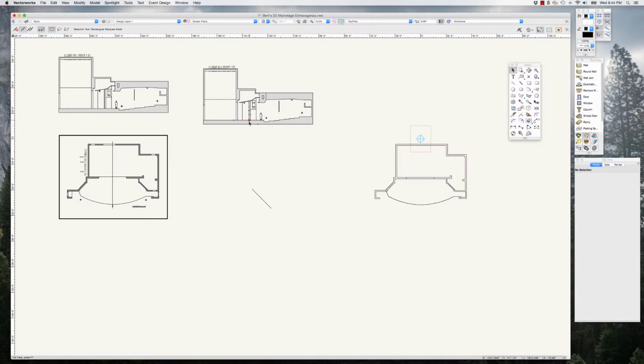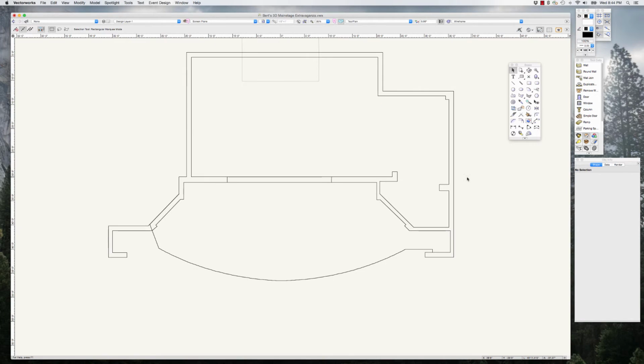The answer is we have to look back at the ground plan, and I need it to go at least from this point to this point. And I might as well just go all the way over to this point. What the heck? In fact, we really could just go from here to here. So that is 71 feet 11 inches, give or take. So 71, escape, 71 feet 11 inches.